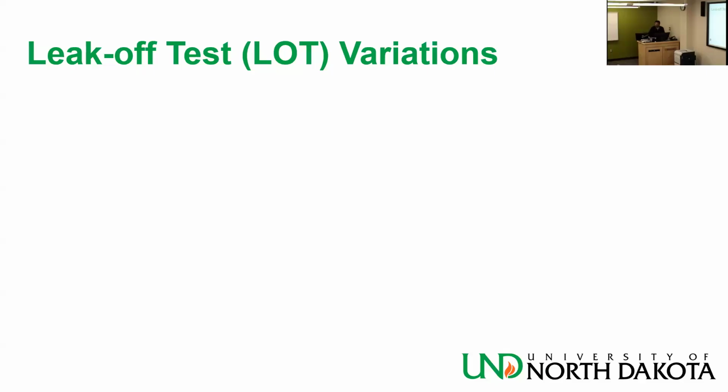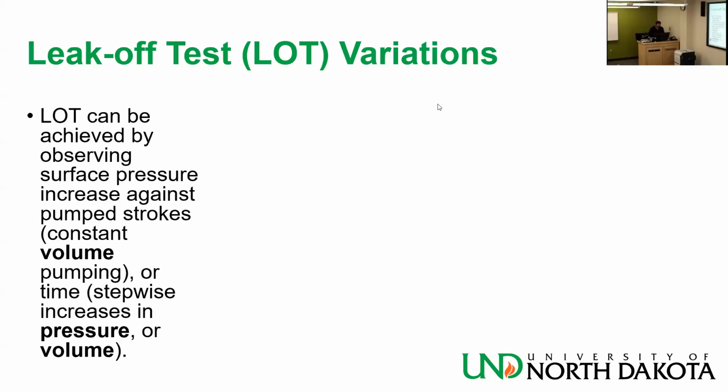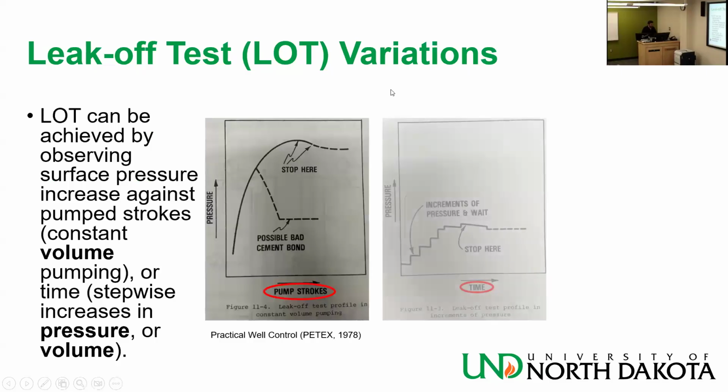But it gives you 3 ways of doing the leak-off testing. One is by observing the way the surface pressure increases with pump strokes, so constant volume pumping, or time, i.e. stepwise increases in pressure or volume. So let's look at some screenshots I took from that book.